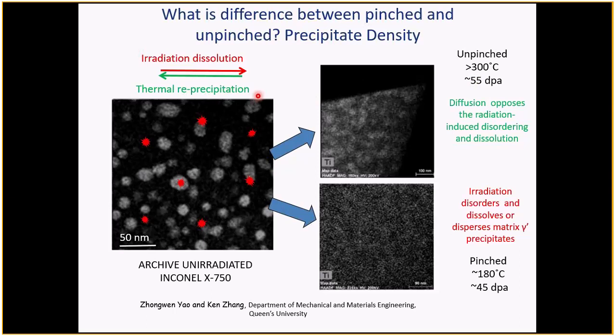At 300 degrees C, this reformation process is going to be very much slower, such that this other process, this damage process, which is also glacial and happens at a very slow pace, in effect, even though you might get every atom displaced once a year, or twice a year in this case, the fact that this is a slow process and this is a slow process, it's the balance of the two.